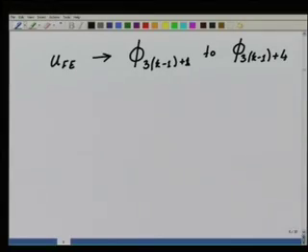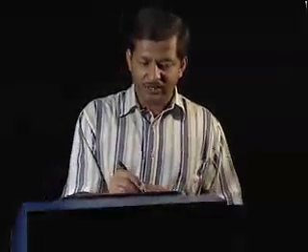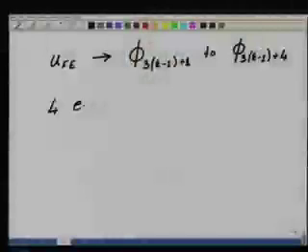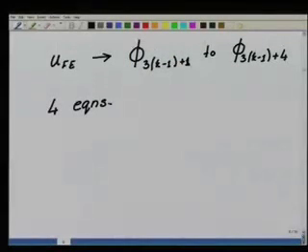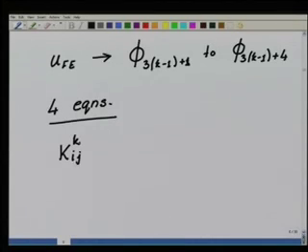So when we make the element equations, we will have how many element equations? Because of p equal to 3, we have 4 shape functions in the element. We will have 4 equations at the element level. And what are these equations? These equations will be the Kij of the kth element is equal to integral over which node am I going to go from? So I will go from x1 of k to x4 of k